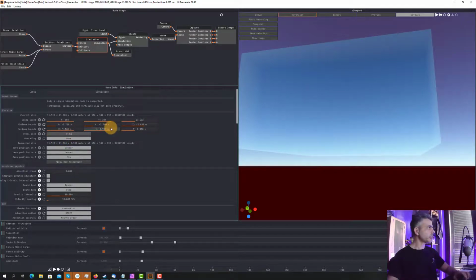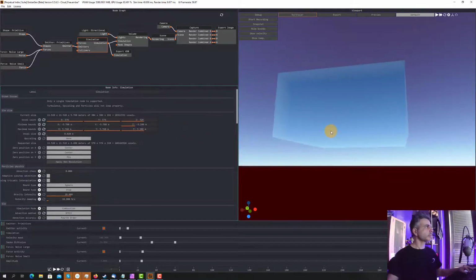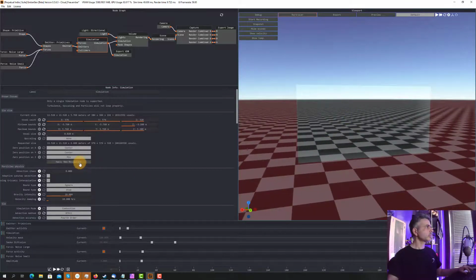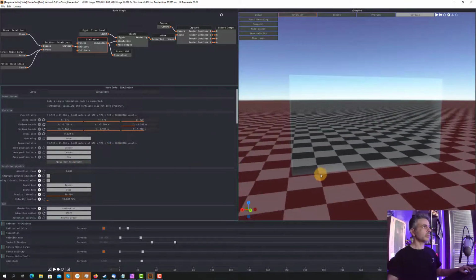So let's go for 0.02, and we go back to the scaling we had before. We should use just a little bit less memory than before, so we'll have a lot of details, but we have a little bit of memory free for Windows and the user interface. Okay, so we will have no problem during the simulation.